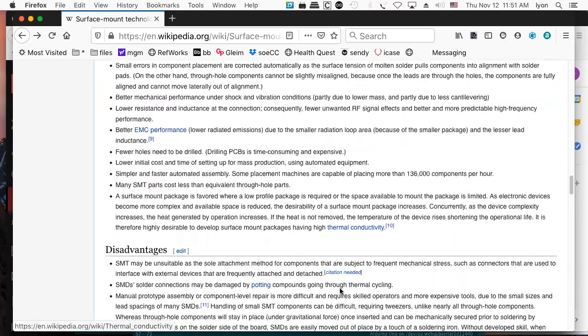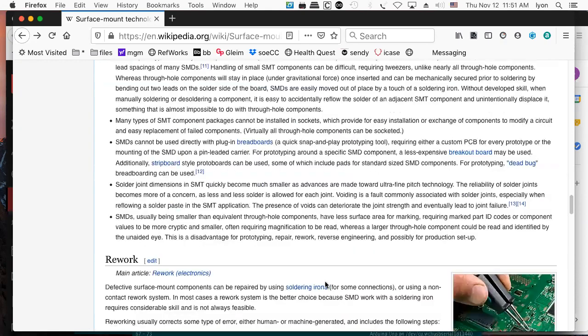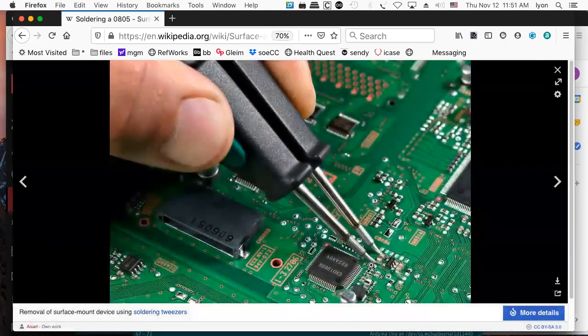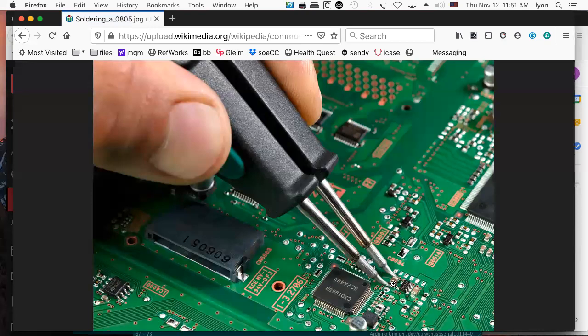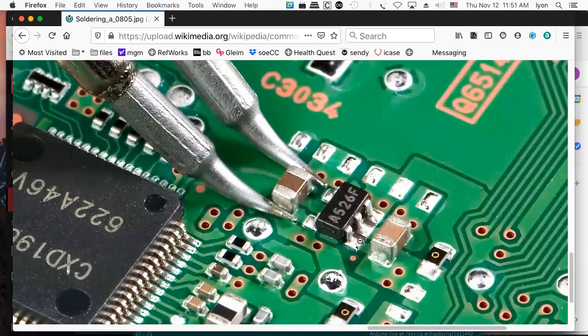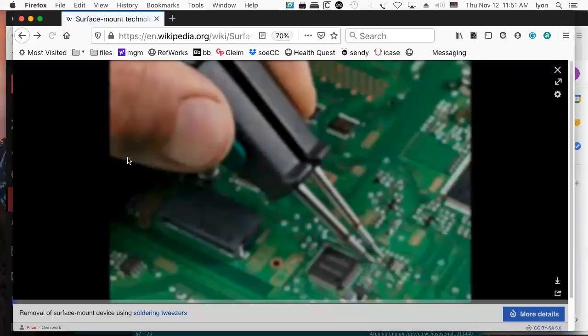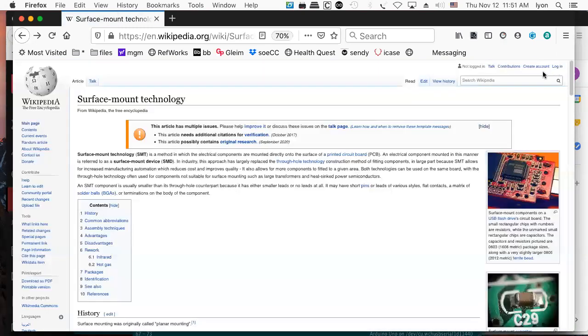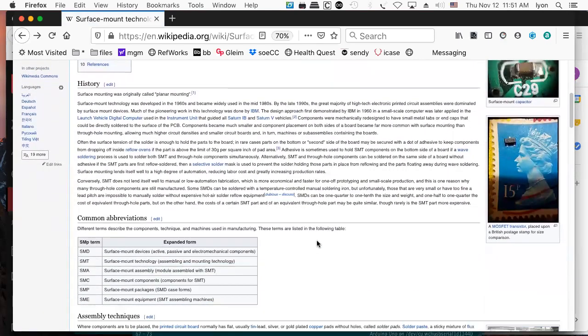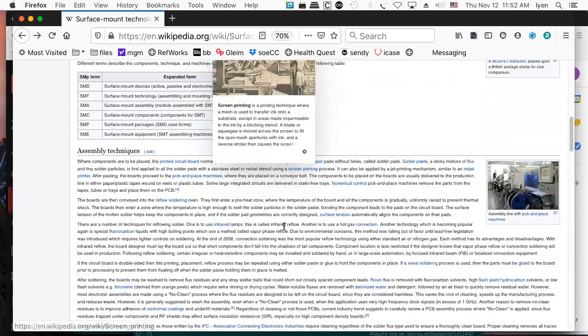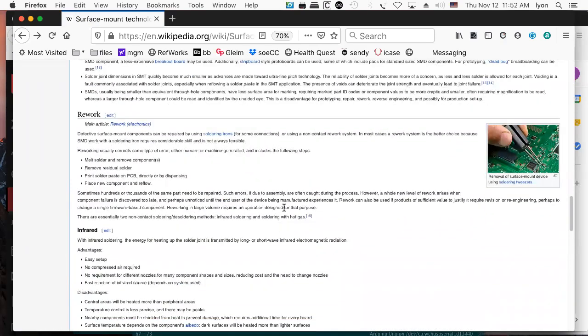Microelectronics has not gotten hobbyist friendly, I'll put it that way. It's tough to work with things like this. I mean, that's not easy. When you make a mistake with this, it's not going to give you a syntax error, right? It's just not going to work. These little guys, if they have a solder bridge, you're going to be sitting there with the microscope going, I wonder where the error is. And you're going to be going through this and you're going, wow, this thing got really hot. I wonder what happened. And then you'll be like, oh no, I've ruined the whole board. And that can happen. So you have to be careful with that stuff, especially when you're doing it by hand.